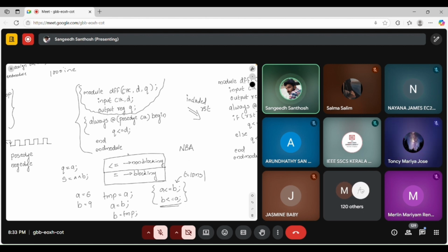At that time, you will check a particular clock, what happens, and in the simulation you will check whether that particular register is getting updated with that particular value or not. Whether our clock is working properly or not. These are all things you need to verify. So even without the definition of the module, you need to understand what is going on inside that particular module.